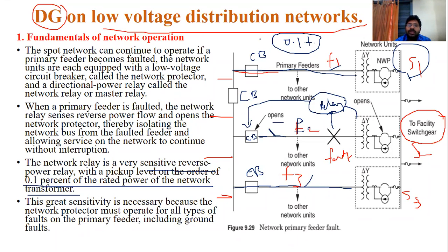You know we have already seen some topics here, the reach of the relay. Whenever you add DC here, the reach of the relay obviously changes. You should keep that in mind while adding DC near the relay locations. The reach of the relay, meaning the sensitivity capability of the relay, is reduced by adding DC directly to this place. That is another issue here. How to handle this, we will discuss later.